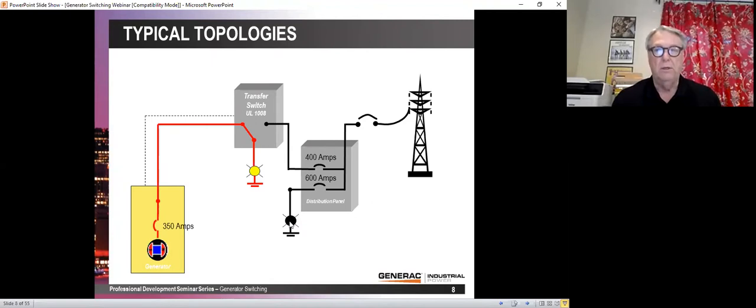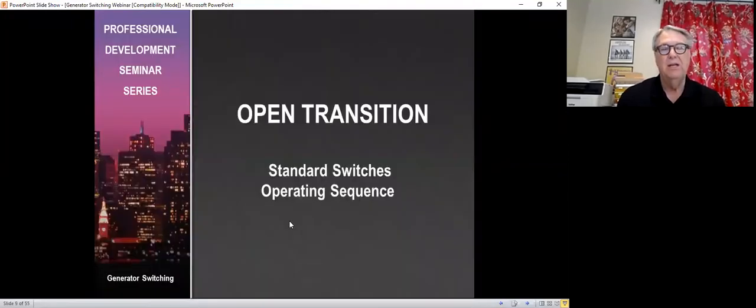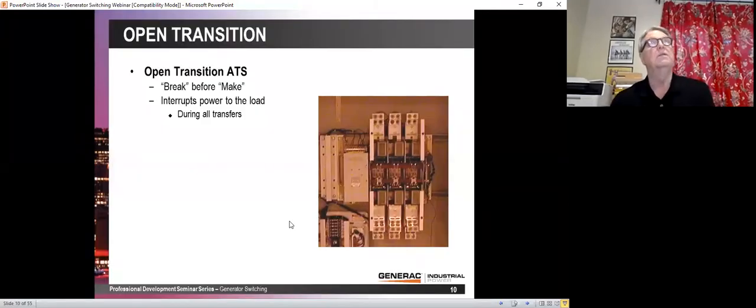And so I learned a little lesson there, and I found out that electricians, having great ingenuity, every time there was an outage, would tend to wire more things onto the generator. So it's a good idea to have your generator with a little extra capacity to be able to operate. Generators should typically be loaded to no more than 80%. That's not because the generator can't do more than 80%. That's called engineering margin, and that allows people to wire things to the generator that you didn't want on there. It also accounts for some things that you may not have realized, like the CEO's office.